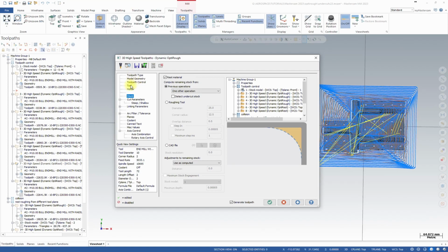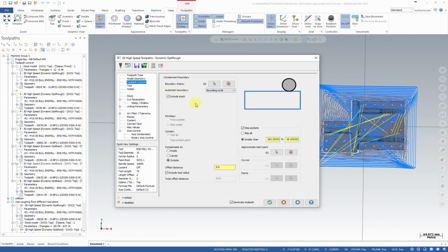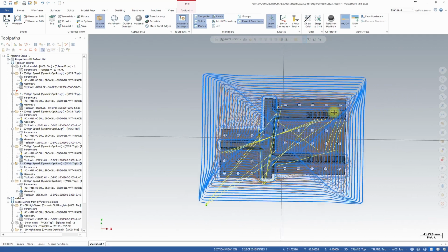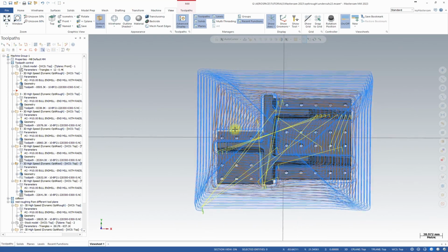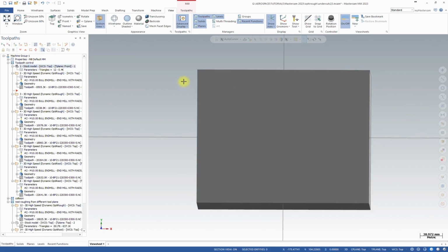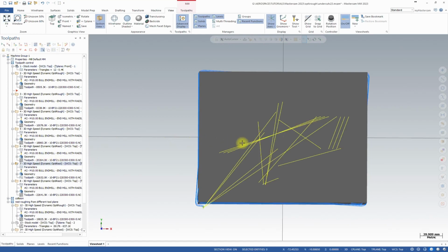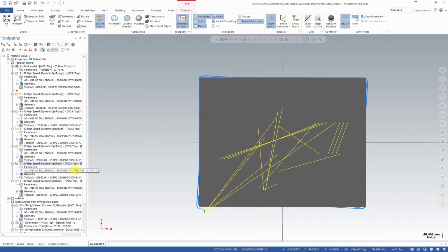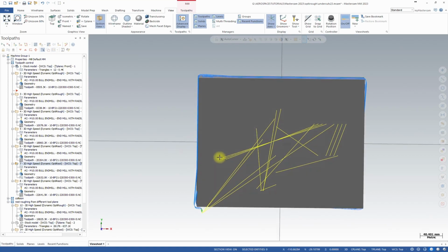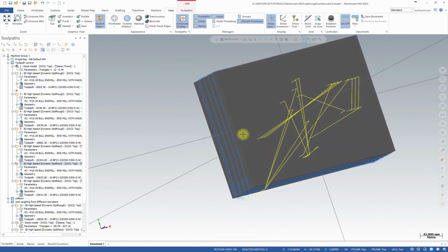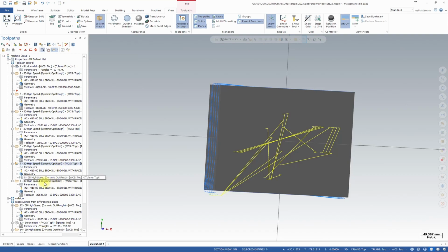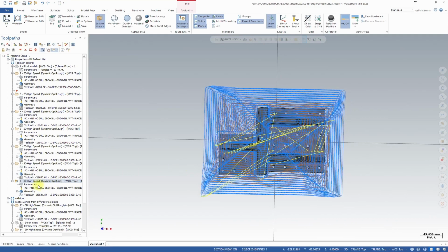And of course you need to remember that on the toolpath control you need to include stock, and in this way Mastercam will produce cuts or passes in the area calculated from model geometry page and stock page, and in our case it's this stock model. And as you see, we are roughing the whole stock model that we selected. And we couldn't do it in previous version of Mastercam without creating the boundary chain.